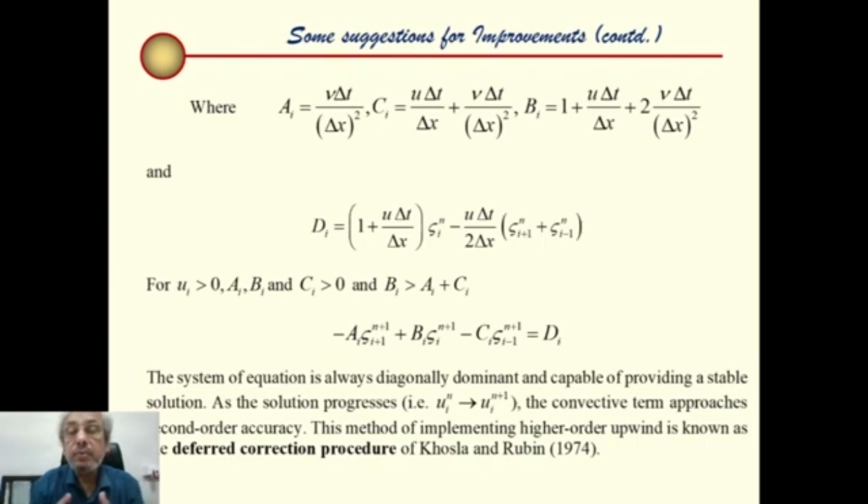We'll introduce a few more issues and higher order upwinding strategies in the next class, and probably then the introduction of the finite difference method will be over. Similarly we will introduce finite volume and finite element, and as I have said, then we will take up real Navier-Stokes solvers using such finite difference, finite volume or finite element techniques.